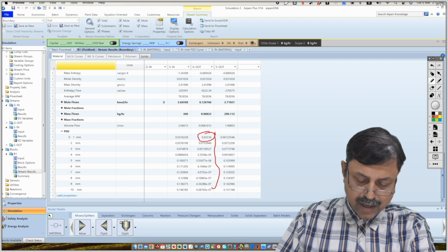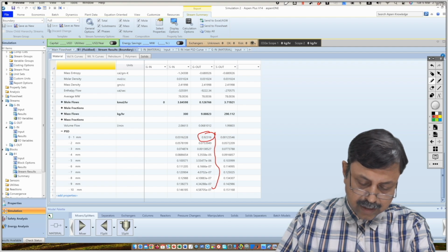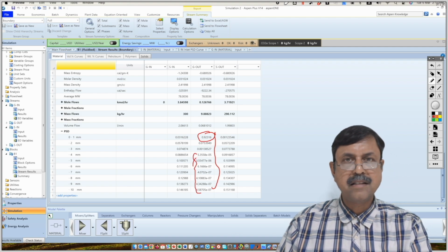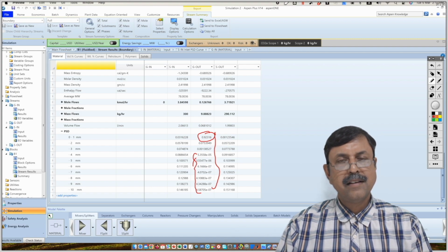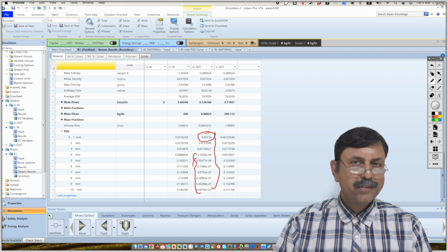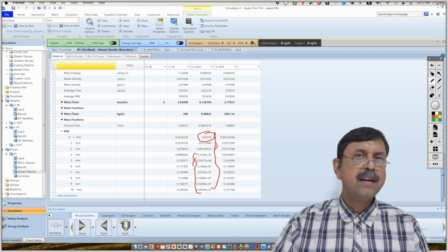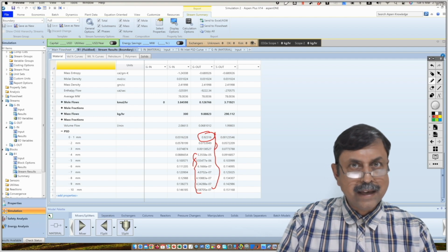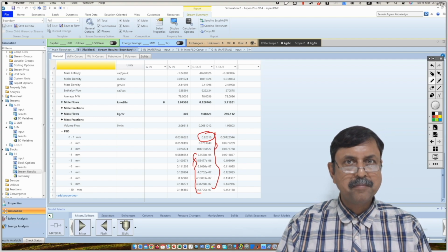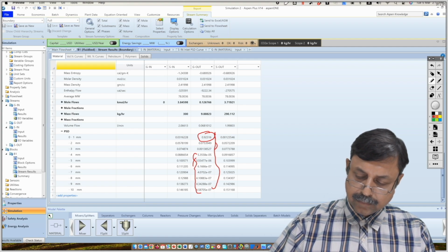And then 7.5% is 2 millimeter, then 3 millimeter, etc. Anything above 4 millimeter is negligible, because those are the heavier particles, so they are not going out. Only the finer particles are taken out by the air due to elutriation. Right? And that is what is expected.